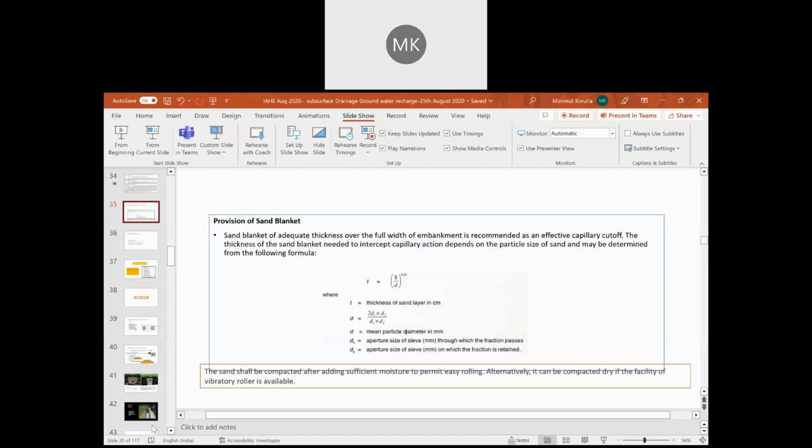Please calculate the width of the drainage, longitudinal drains or cross drains, whatever the requirement. You will see that the depth and width are very much higher than whatever we think normally, because of the type of catchment area which is collecting the water. Don't consider a 100-year return period or anything; that's normally for dams and all.